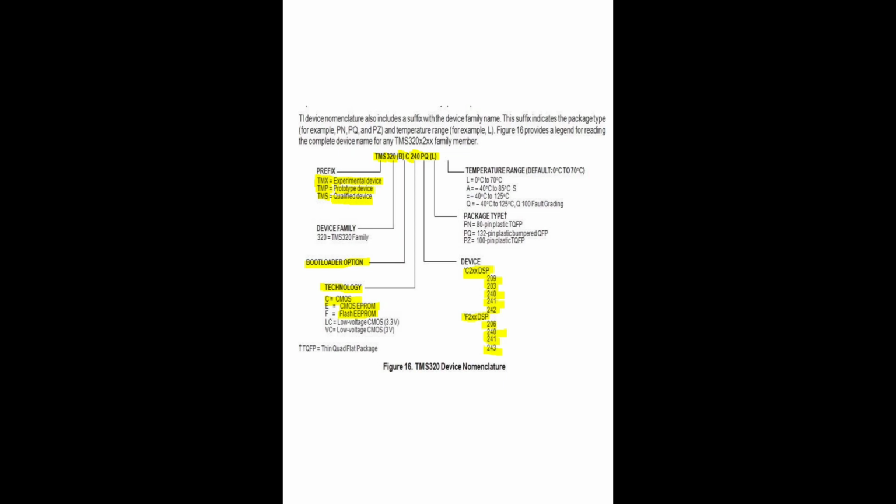And then PQ is nothing but the same IC which may have an 80 pin package, or the same IC can be with 132 pins, or the same IC with 100 pins. It depends upon how many pins are multiplexed and how many pins are given separately. Multiplexed pin means like AD0 to AD7. That means a single pin will work for address as well as data.